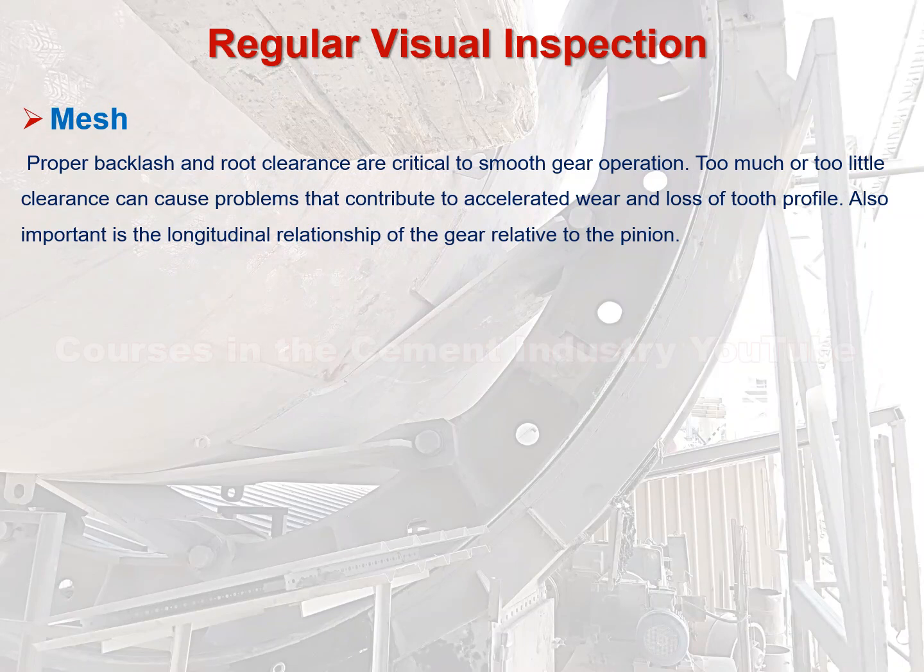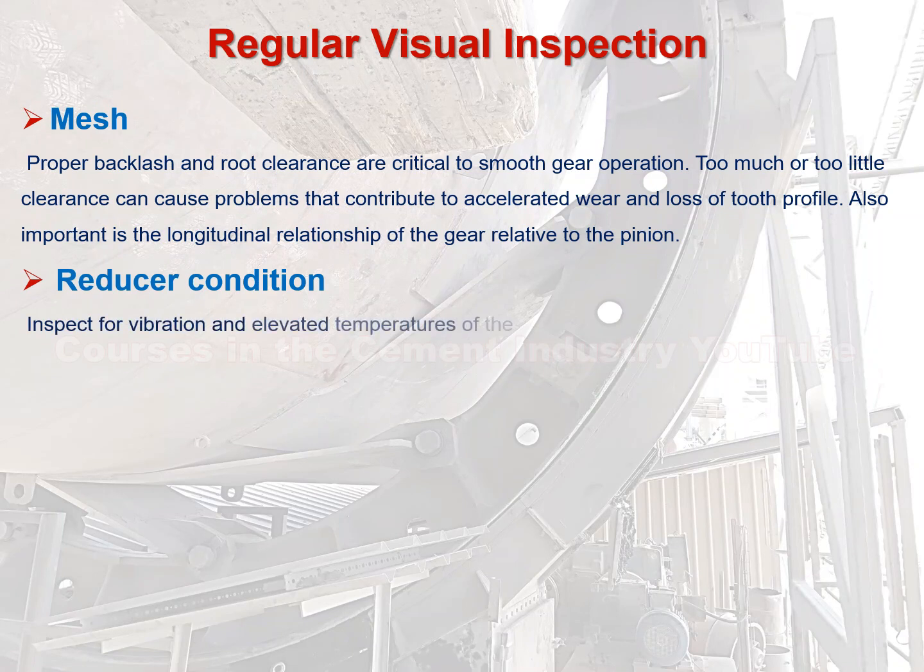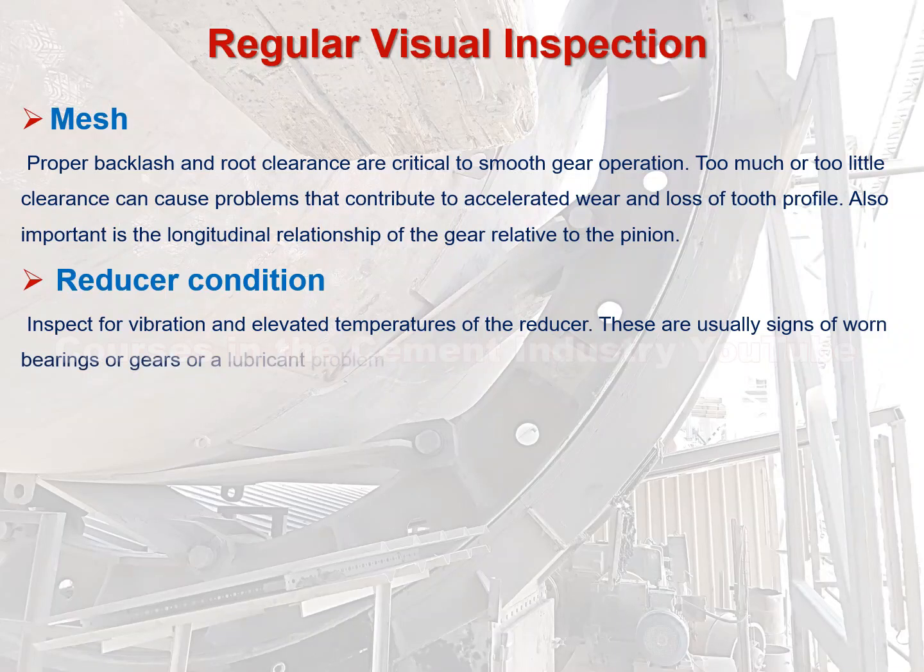2. Reducer condition. Inspect for vibration and elevated temperatures of the reducer. These are usually signs of worn bearings or gears, or a lubricant problem.